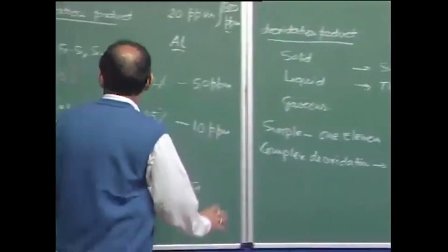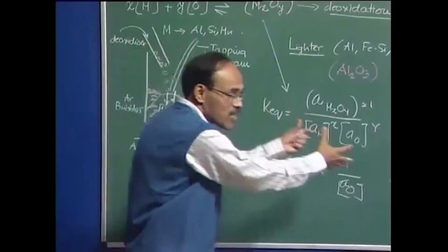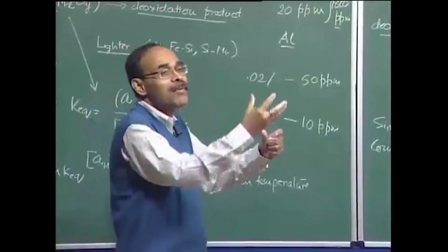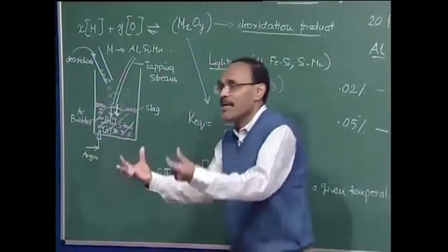So therefore, once the ladle is filled up and you are taking it to subsequent stations, you get some time, and in that time the deoxidation products which have formed deep inside the system have a chance to float up.